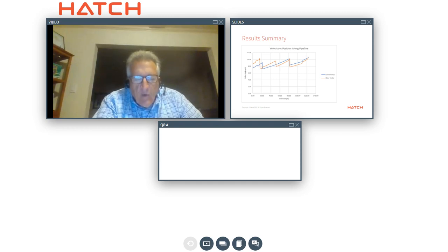And all throughout the calculation, you notice that Colin was always looking at the summary chart and the color being shown on the right side, whether it was blue, green, or yellow. That color and that designation of the mode of conveying is determined strictly based on the velocity of the system in each of those segments of the convey line.